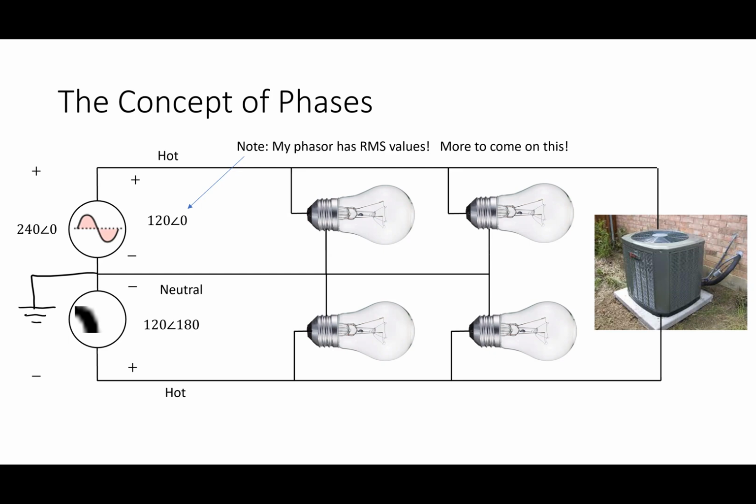All right. Most of your outlets, like these guys, are hooked up to one of the two 120s. One of the two, all right? Some of them, you don't know this, but they're 180 degrees out of phase. It doesn't matter to your computer or whatever when you plug it in, but that's what you got. All right, so that's what a single phase system would look like.